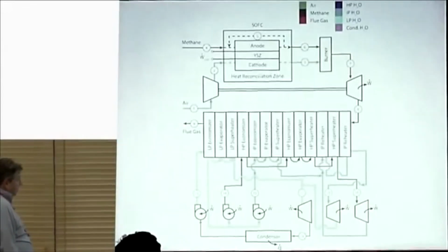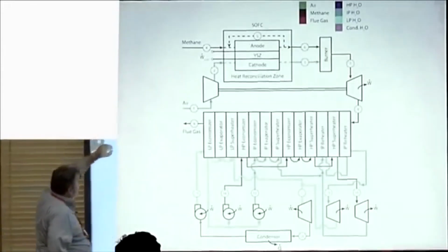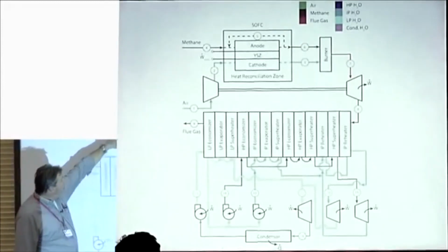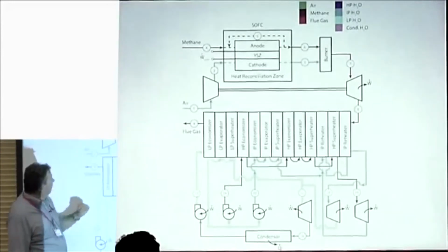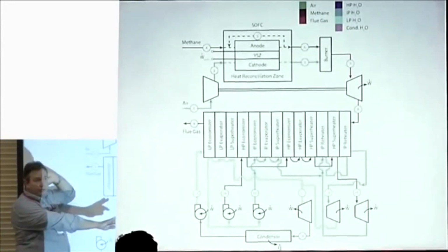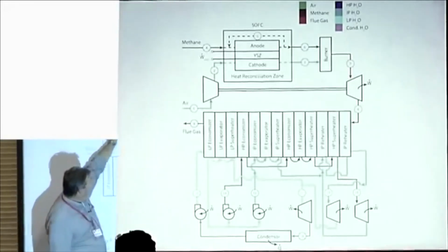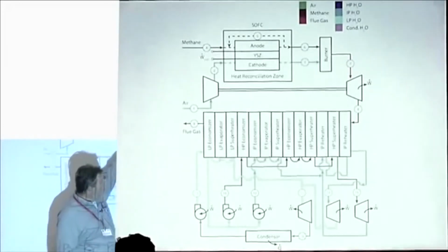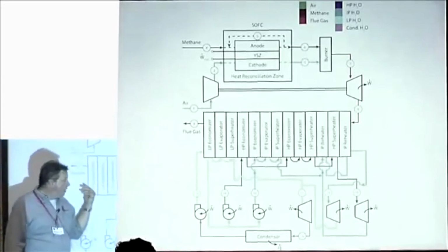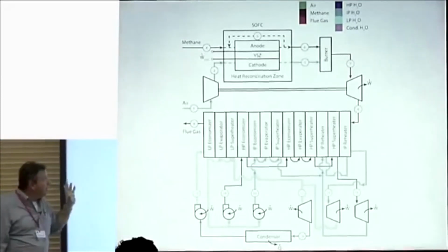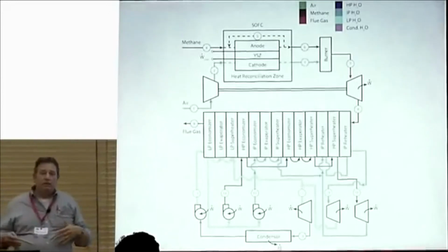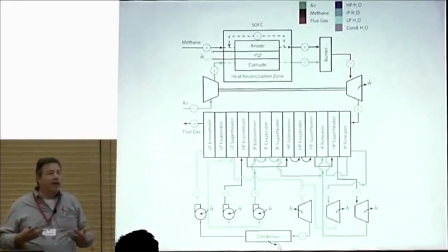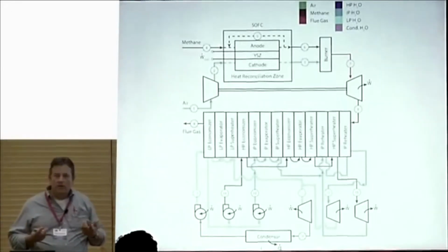This is modeled. This is work of one of my students, Rebecca Pass. Methane coming in. This says anode recycling on the SOFC. So YSZ and SOFC that's doing the pre-reaction. The air is coming from a split gas turbine, so state-of-the-art gas turbine. Coming in through the cathode, we resolve the heat integration inside of it, do a post-combustor from it across the turbine, 3 pressure level HRSG on the backside. And basically our interest in this is what does it mean to get to 70% LHV efficiency in terms of managing exergy? What is it about this system that's getting you to that number?